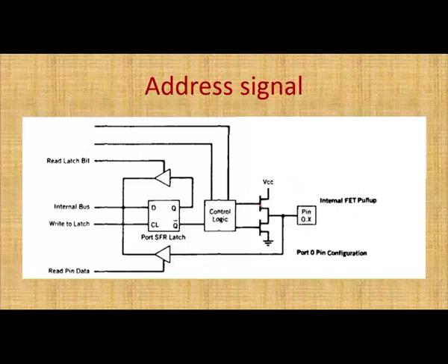This is the address signal. So here we are using address and data signals, and this is a control signal. For read and write operations the control signal is 0, and for address and data the control signal is 1. Control signal 1 means you can consider this a mux. So this value is I0 and this is I1. Normally, how do we select between two signals? We use a 2 cross 1 mux with I0 and I1, so only one output comes, based on the select signal.